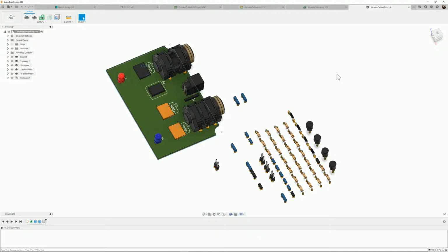That means when I go to do thermal analysis, also in Fusion, it has the material properties assigned, and they will behave like those real materials thermally. And also in rendering. You can make LEDs in your Fusion library and put a chip inside the middle of the package. You can make it translucent. STEP doesn't support translucent bodies properly, and most other ECAD tools won't show translucency from a STEP model.